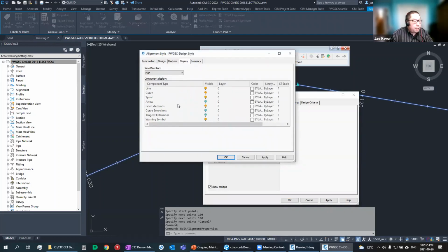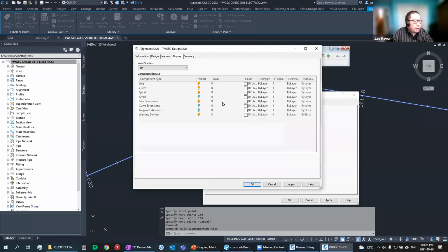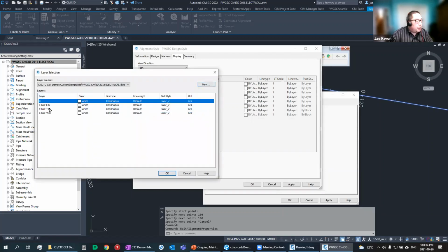And right now, this is why I usually don't get rid of all layers for the base drawings, because right now it's all at 0. But if you really wanted to clean house, that is something you can do. Right now, I'll just select all those line elements and put them on the ENW-LIN layer.